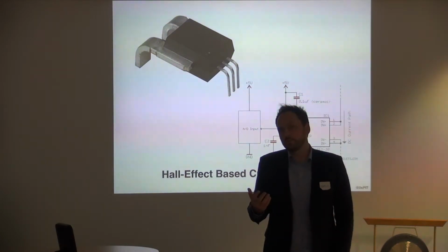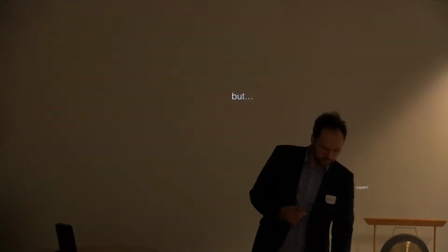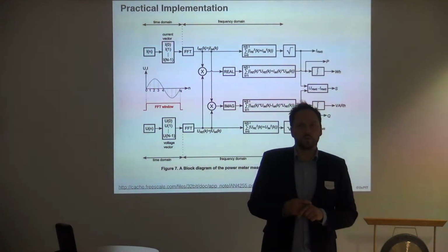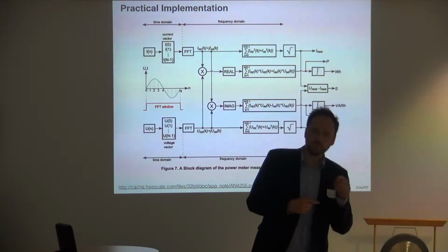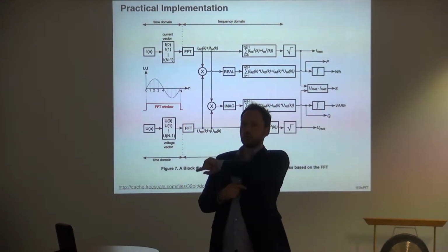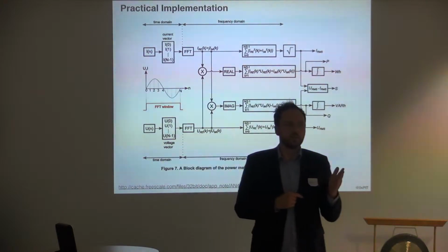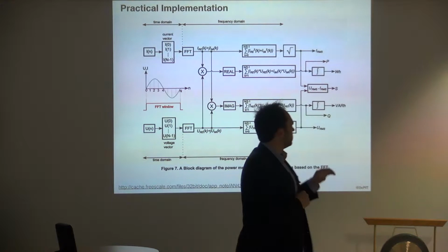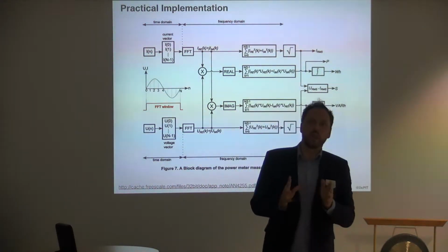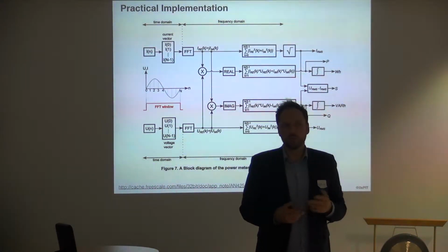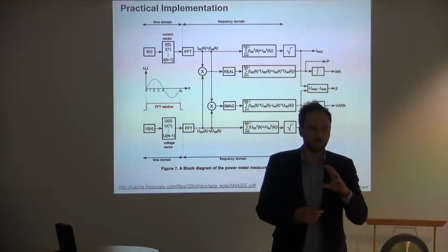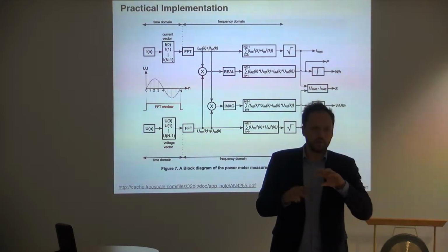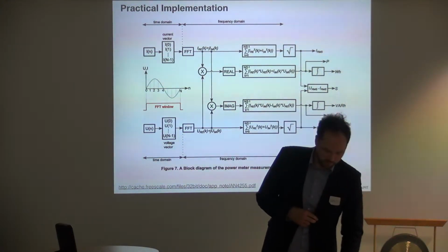But if you're a good engineer, which is a lazy engineer, I forgot. It's still rather complicated because you have just the core power, and then you need to integrate over the sine wave of the alternating current to actually calculate the real power you will pay for. And this is a cool implementation which is okay on a DSP but not on an Arduino, which uses FFT to calculate the real power and all the power parts out of the measurement of the sensor over time.